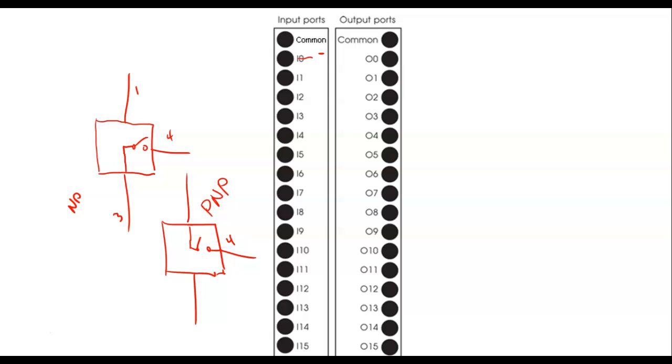So on these solid state sensors, you can't tell from the symbol whether it's sinking or sourcing because they all wire the same. And some of them have a 2. So they'll have a 2 coming out. So they're going to have a normally closed and a normally open, but it's still going to be sourcing or sinking. So a 4-wire sensor, and what's the colors?